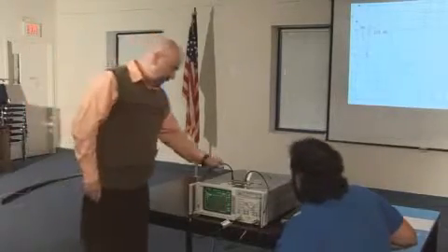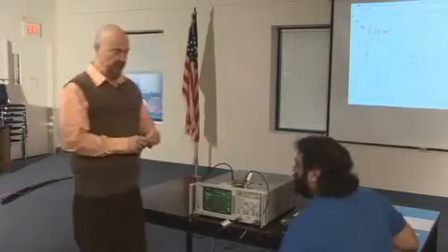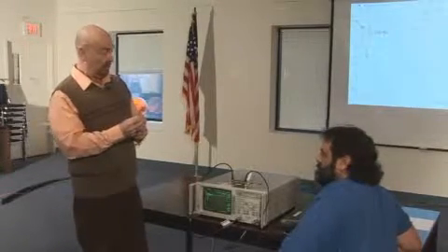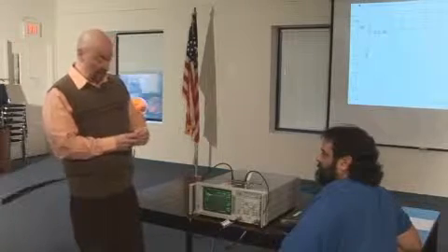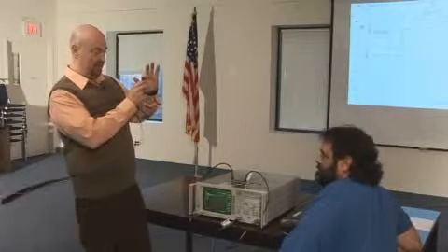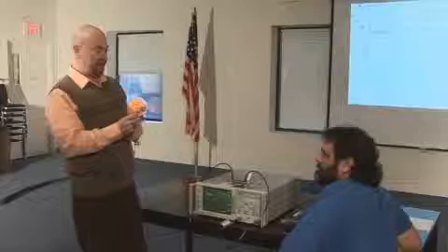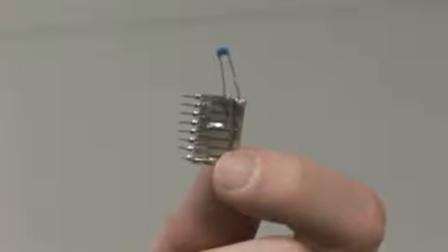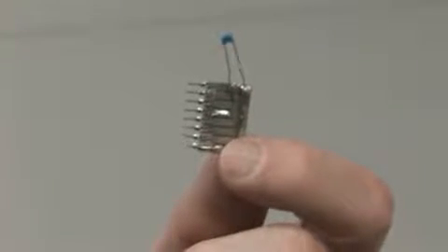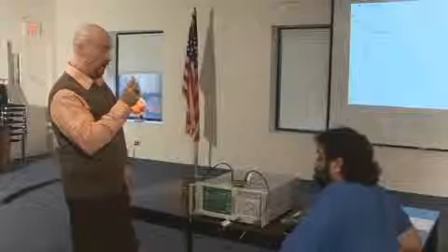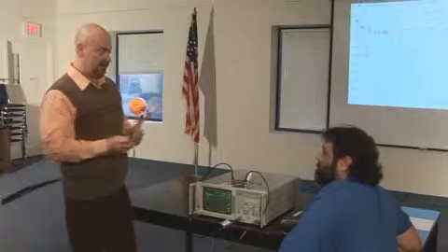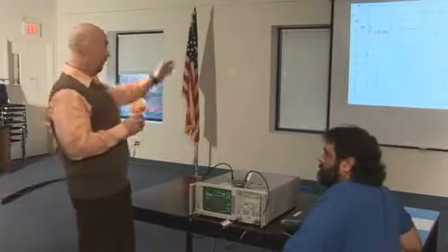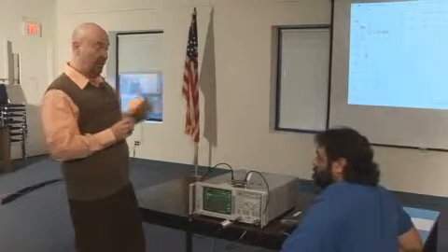Yeah. The real problem is that on this long-legged capacitor, there's more happening, especially as you move up in frequency, than meets the eye. You have the capacitor itself, the plates and the body. But as you move up in frequency, the legs, the leads, start acting more like plates of their own with air as a dielectric between them. So your capacitance effectively decreases because there's some parallel with it, and your frequency shifts up accordingly.